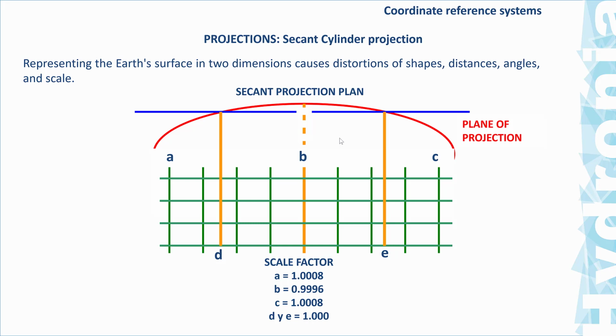So if you have a city that is not more than a few tens of kilometers wide, and you use a projection there, you are doing a very good approximation of the curved surface that it is in reality. So these errors may not pose an issue when doing modeling, and that's why we use that plane projection that is much simpler to handle than the spherical projection.